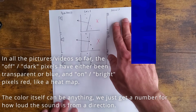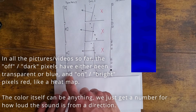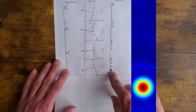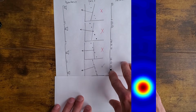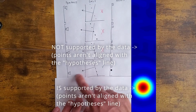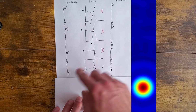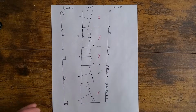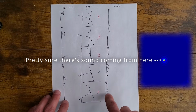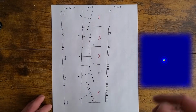If there's a lot of points on that line, however, then the data does support that there's a sound coming from this direction. So that pixel gets a high number, or it's bright. And so we scan through for every single pixel in the image, do this process, and then light up the pixels that are sort of where the data supports that there's a sound coming from that direction. Do this for the whole image, and you get a map of how certain you are that there's a sound coming from that direction, and that map is the image.